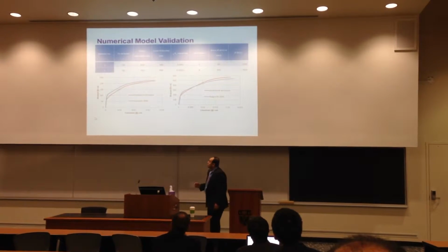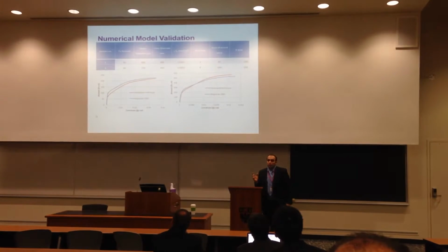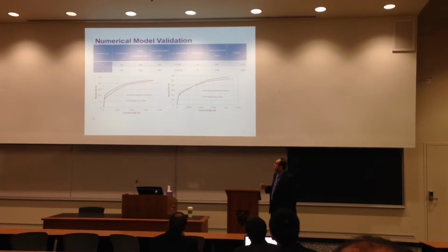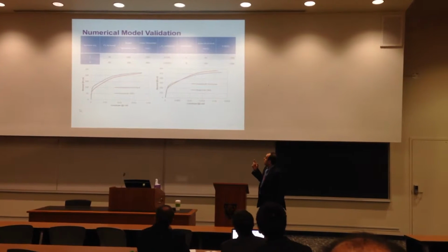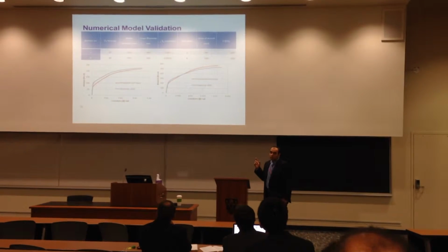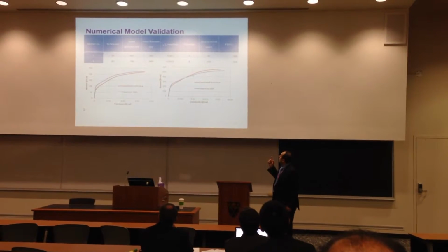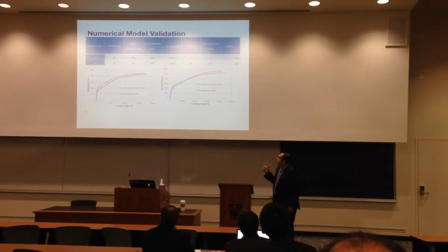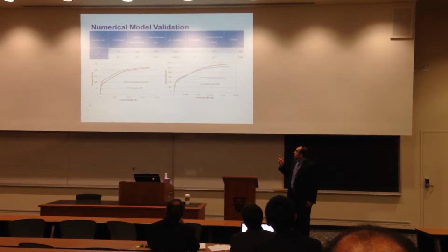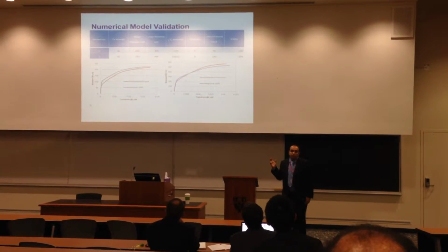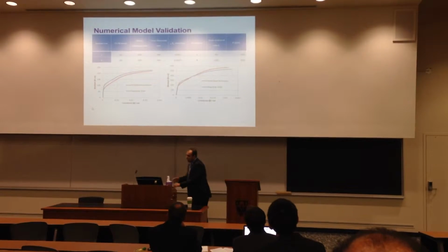To validate the section analysis for the developed technique, two circular hollow pre-stressed concrete sections are investigated for various outside and inside diameters, various initial pre-stressing strains, different numbers of strands, different steel areas, and different compression forces. The moment curvature for each case is compared with the Response 2000 program, and this shows a big agreement between the developed technique and the Response 2000 program, so we can rely on the developed technique in the section analysis.